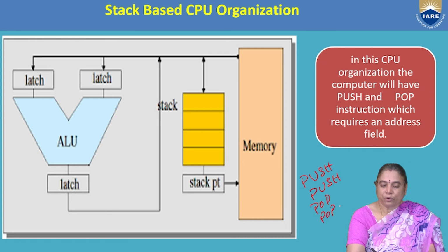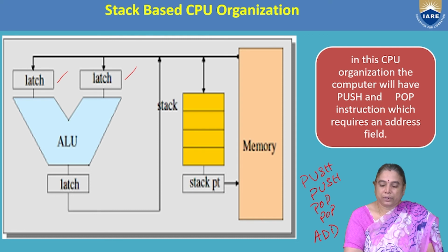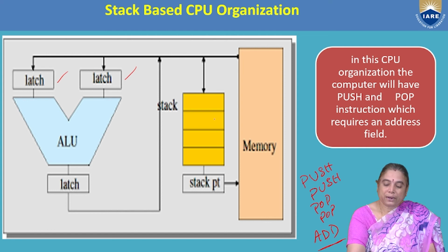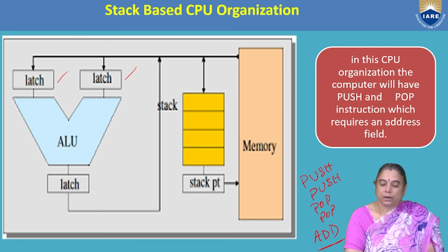Those have to be stored in these two latches. Next, we can simply perform the add operation. So this type of instruction we generally call zero address instructions. We are not specifying any operands. Those operands are readily available in the stack and can be popped to the latches in order to perform the arithmetic and logical operations. So this type of architecture is called stack-based CPU organization.